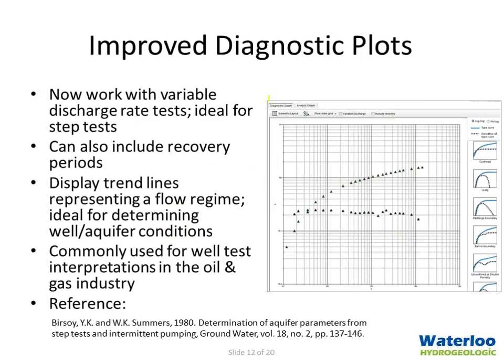The other improvements we've made are as they relate to diagnostic plots. In the previous version of AquiferTest, these diagnostic plots only worked with constant rate discharge tests, so we've removed that limitation. Now you can display these diagnostic plots for variable rate discharge tests, which is ideal for step test analysis. You can also include the recovery periods, for both recovery after the pump's been turned off or even recovery periods during the step test intervals.